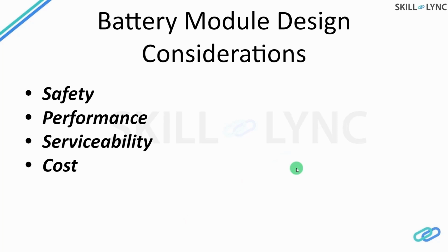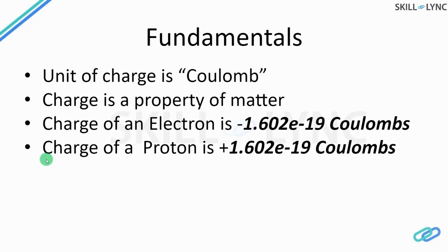And as I mentioned a slide back, typically when you are thinking about the number of modules and the number of cells per module, these are the things that you look at. You look at safety, performance, serviceability, and cost. And depending upon the industry that you're working for, these parameters would change. Alright, so that being said, if you want to learn more about batteries and understand battery ratings, you need to have strong fundamentals in basic electrical engineering concepts.